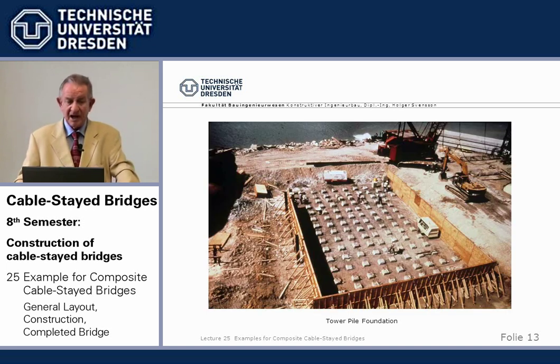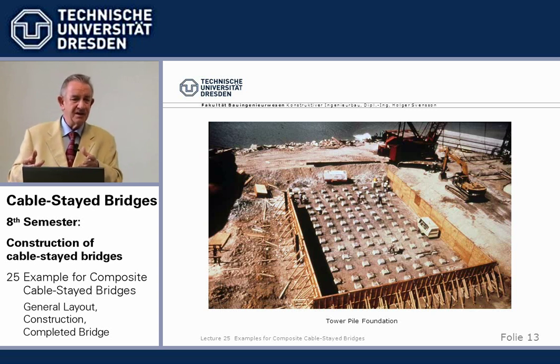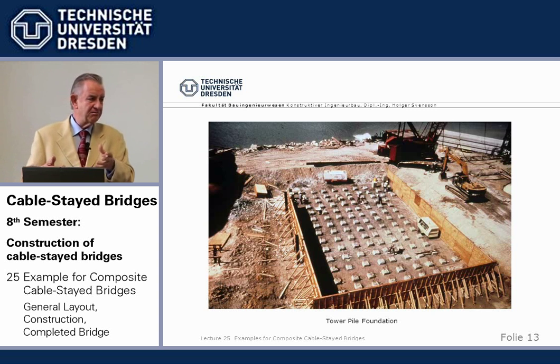Then we are in the Houston area. It's alluvial soils, which means very fine clay, which came in with the water, mud, better said, mud. And the rock is down some 300-400 meters, no way to reach it.